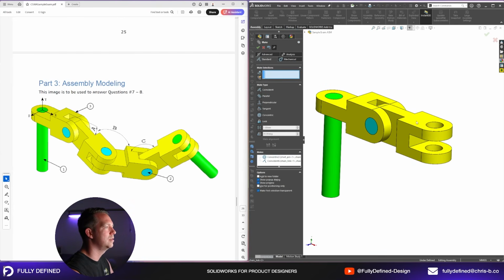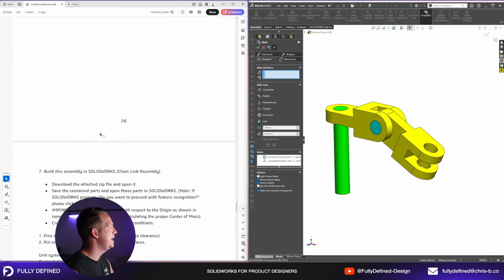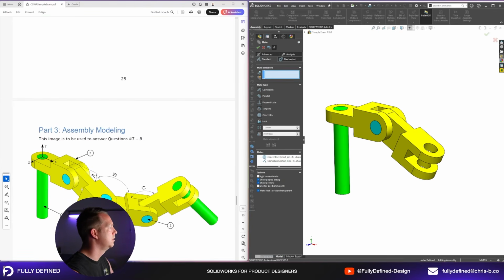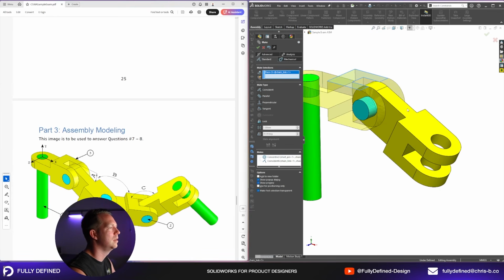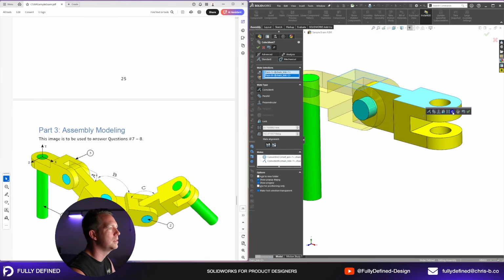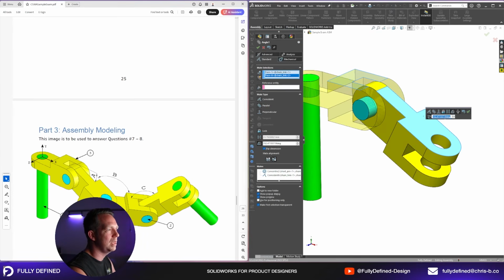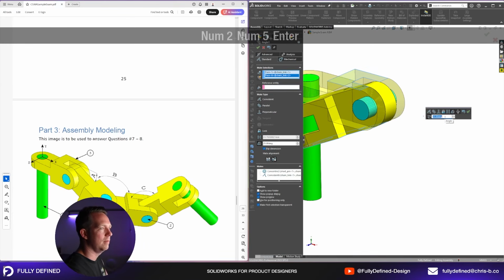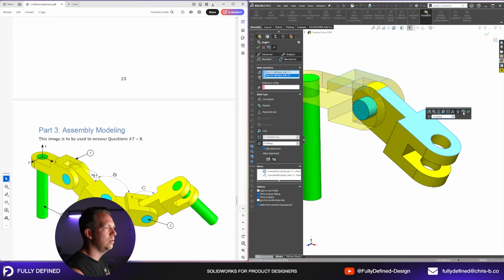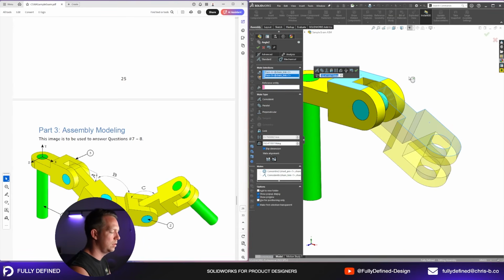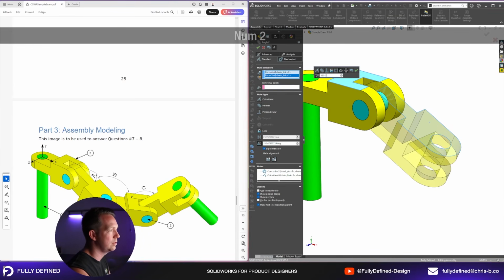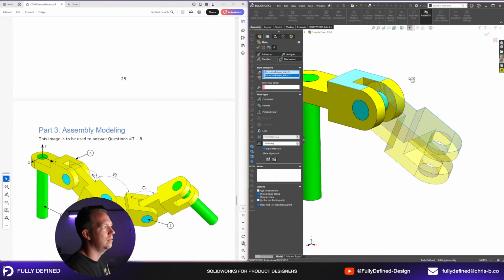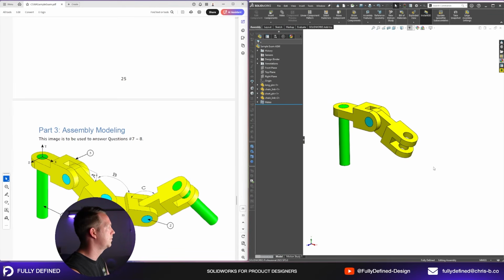That's asked to mate an angle. So angle A is 25. Well, in this example, I'm not going to do global variables. I'm just going to get the angles in there. So I'm going to select this top face and this face. I'm going to select angle. Now I can see the number here, it's giving me 152. If I put in 25, it's going to flip it, right? Don't want that. So undo, try again with the angle, but type in 180 minus 25. Then you'll get the correct dimension you actually need. Okay, so I've got that one.